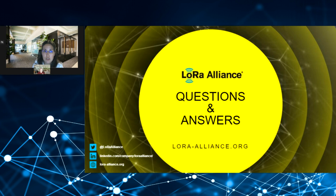We were using a standard Nucleo board for that. And I'm sure you can find this open source on GitHub, and then compile it. You only have to compile it in different ways, one for the end device supporting relay and one for the relay supporting relay. In both cases, you have to ensure that the certification port is enabled, because the LCTT will send testing commands on the certification port 224 to control the relay and the end device during all the tests.